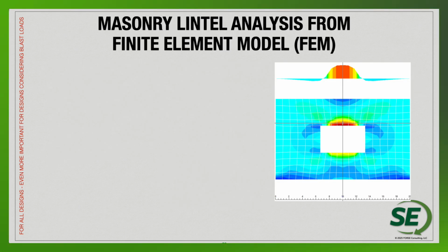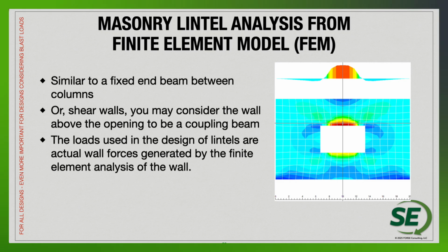To be able to do this, we're going to have a finite element analysis that's going to be really critical for not just looking at the lintel design, but looking at the overall elements of design. Looking at a masonry lintel is something that we can do with the use of a finite element analysis. We can look and see how the lintel element is able to distribute the forces to the wall panels on each side of the opening.